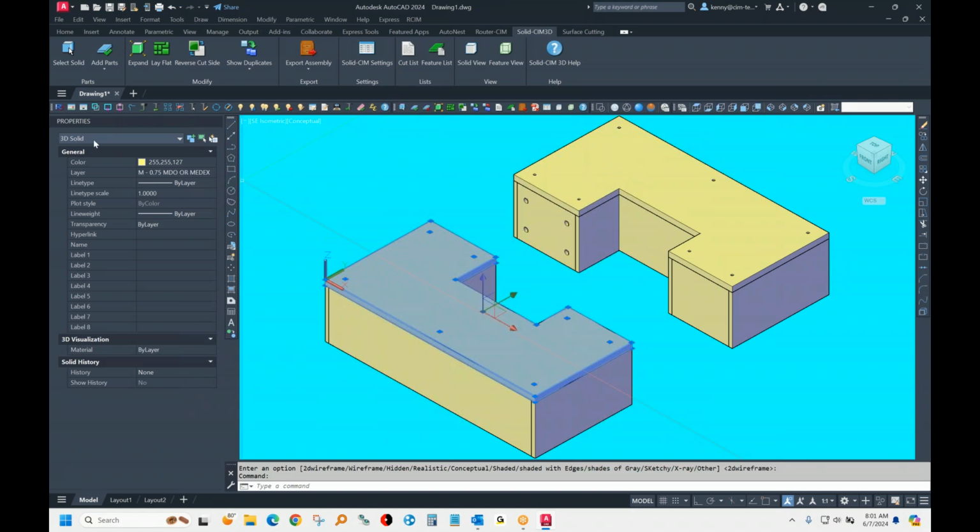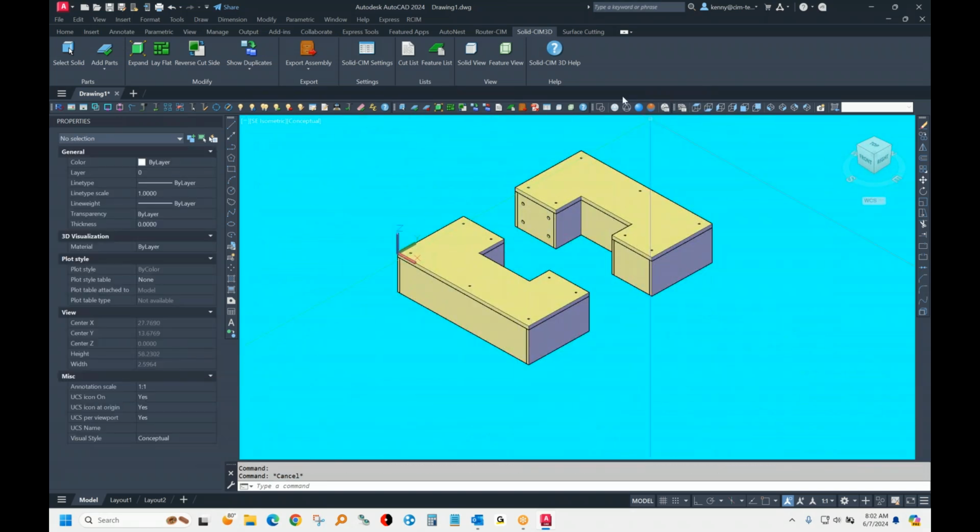And it's got parts. You could put the part name in here and you could put label fields in here. Unfortunately, this layer does not indicate anything. You can make that a material and that'll be the material, so you could use the rmat command for materials. Rhino files come in, but they don't have a material and they don't have a part name. Actually, sometimes they do have a name. You could put in a name and label fields. Otherwise, it's just going to start naming those. You could type the name on each one of the parts.